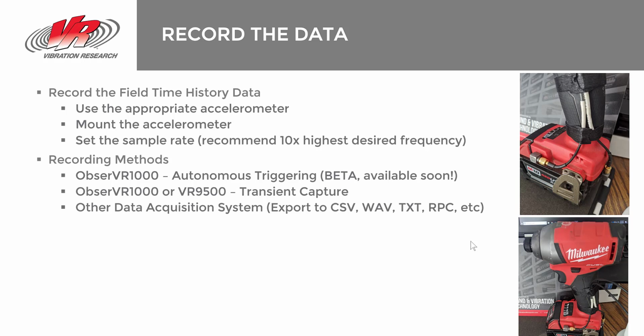VR9500, have it connected to a laptop or PC, and utilize the transient capture software in Vibration View. If I use this transient capture software, I could set up my graphs and my analysis so, as I acquire these pulses, I can automatically calculate all of the plots that I want to look at for comparison and analysis and save that as a data file.